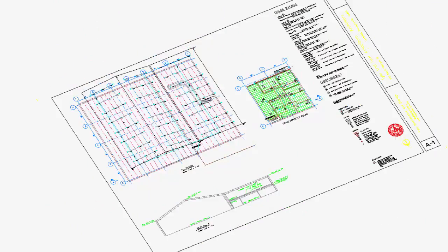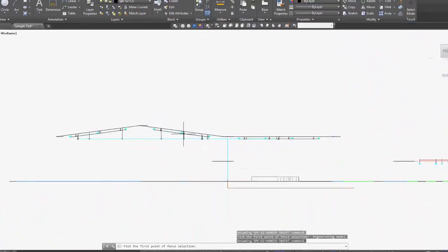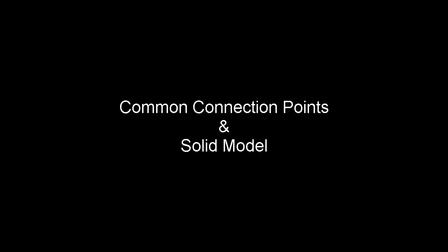The hanger rod lengths can be set, as I said, to an absolute elevation or to a standard center to center length. But by using control surfaces, we can cut the rods either above or below that control surface for drop-in anchors, bottom beam brackets, whatever you need.